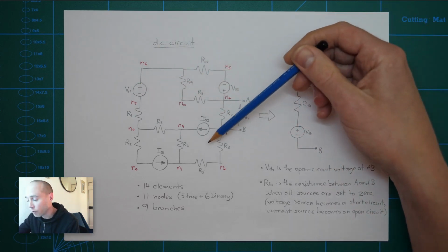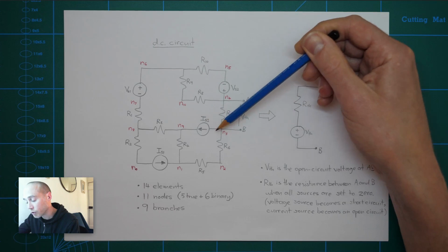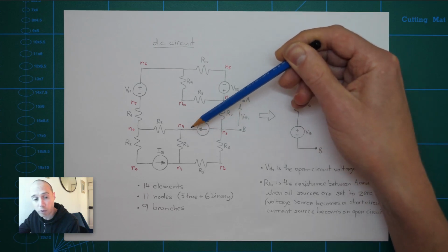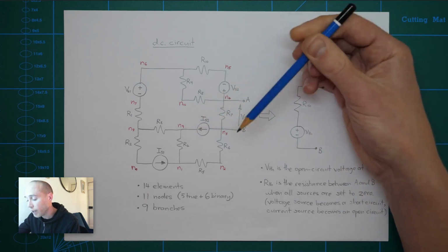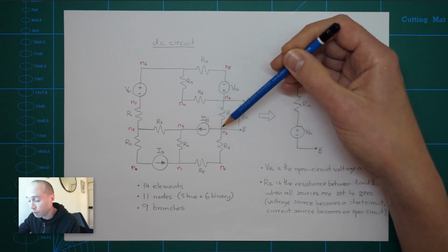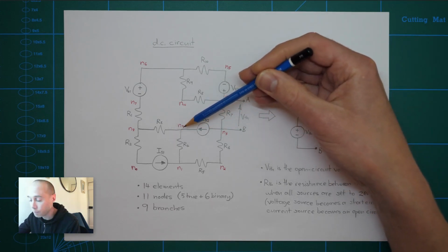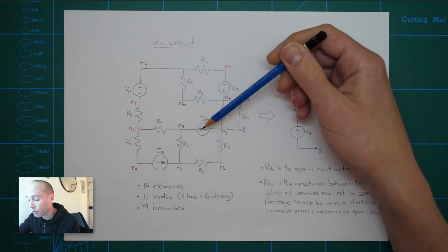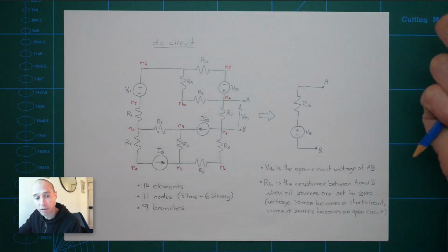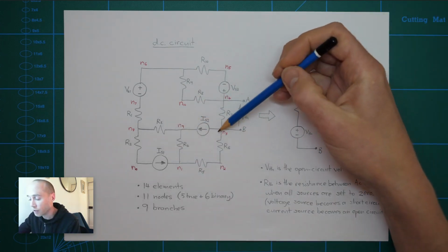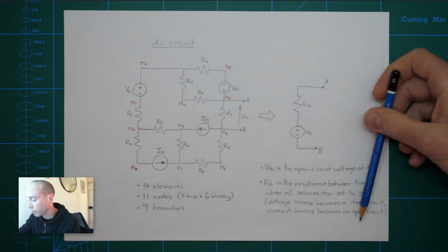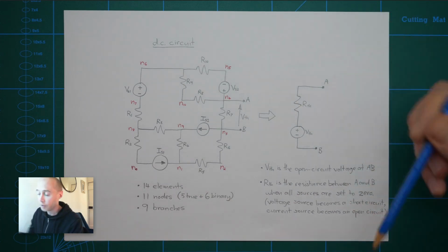On the other hand, a current source defines the amount of current flowing through that branch in the network. If a current source is reduced to 0, it means there's no current flowing along there. So it's basically an open circuit. It's as if you just plucked that element out of the circuit and there's no path for current to flow through, so it becomes an open circuit.